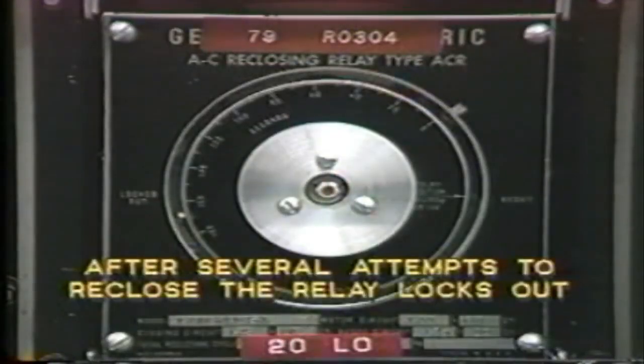However, if the fault is permanent, for example, perhaps a tree limb has fallen onto the line, then the protection will sense that the fault condition persists and will trip the breaker again. The reclosing relay may be set to lock out at this point, or it may be set to permit one or more attempts at reclosing.